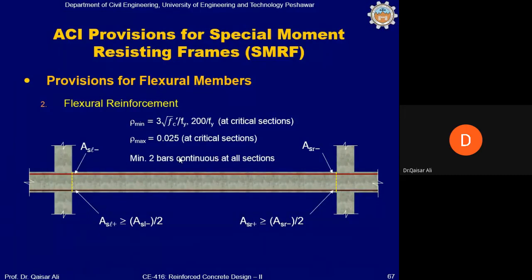Okay, in the frame subjected only to gravity load, the bending moments at the ends of the beam on the bottom side of the beam do not exist. So these are new bending moments which only exist in a beam which is part of a moment-resisting frame, and the frame is subjected to seismic actions.